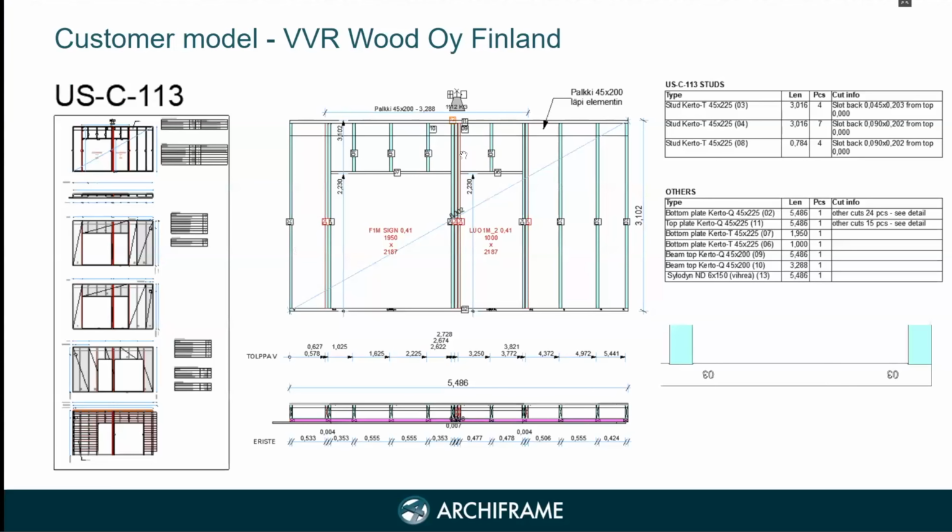And the production drawings. So not only the 3D model, you will need these projections of your prefabricated elements to be able to build these. And I love that on those element drawings, you also have the weight listed on top and also the balance point. Yeah, that's right.